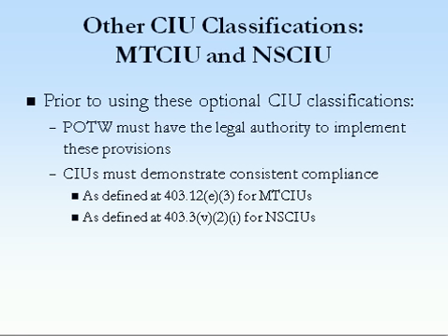Both the classifications of middle-tier categorical industrial users and non-significant categorical industrial users have preconditions that must be satisfied before such classification and categorization may be granted. First and foremost, note that the phrase categorical industrial user is still in their classification. These facilities are still subject to the categorical industrial standards.